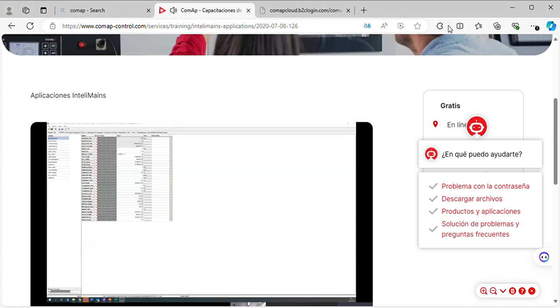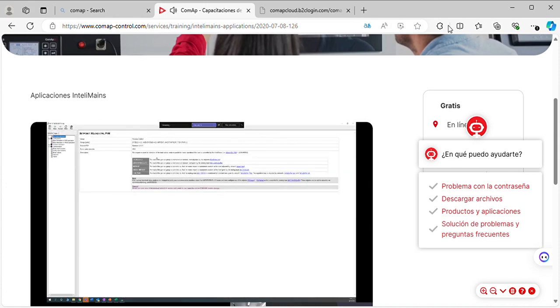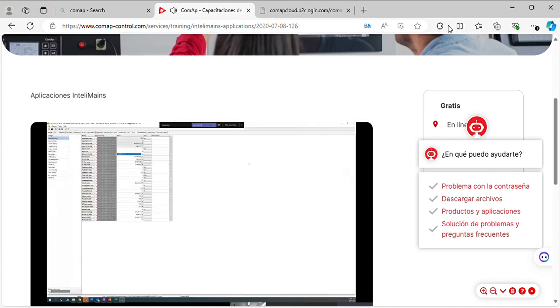There will be a help window opening up on the ComAp, and it explains all of these functions which are listed, the 5 functions, and how they influence the operation in real time. Now, if I choose my system base load to be external, that means I want to configure the base load by using a potentiometer and not by having a fixed base load of 1000 kilowatt.